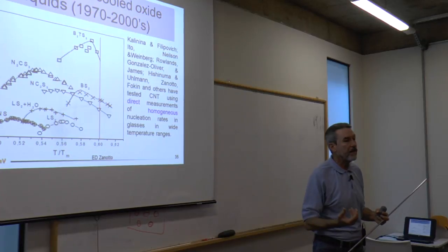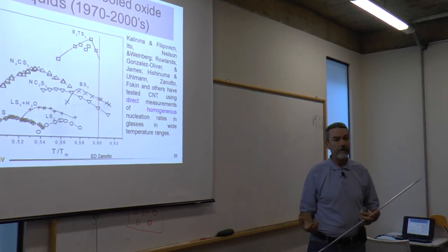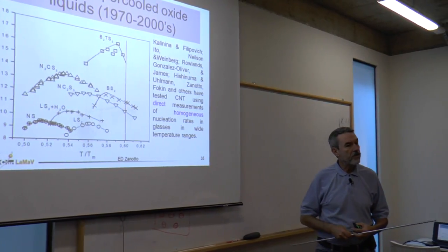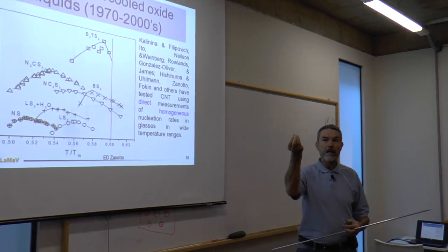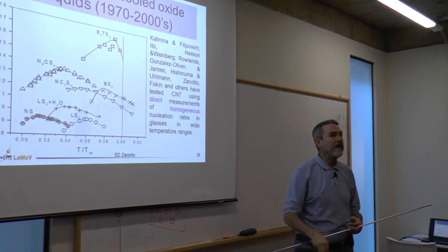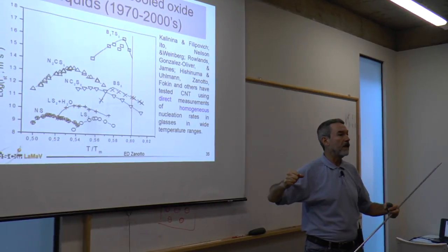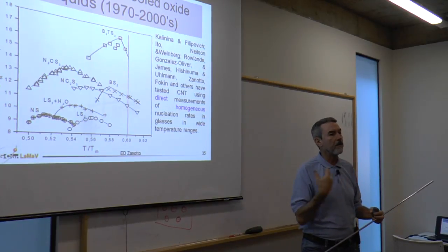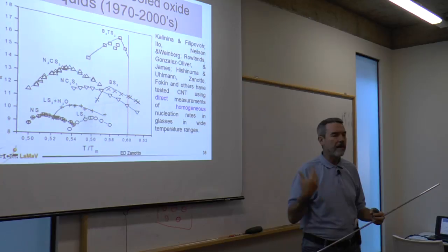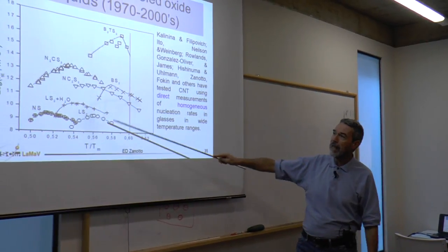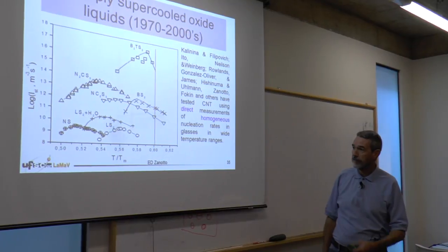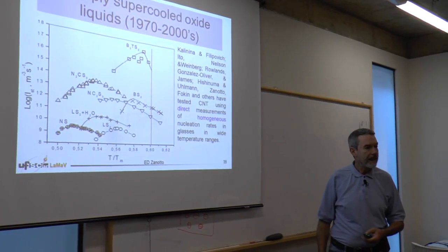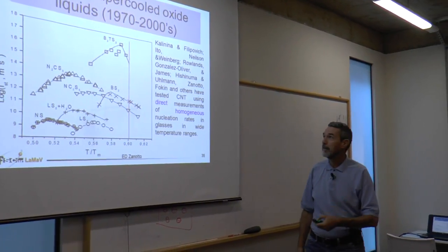And they're very viscous systems, so they're friendly enough, allowing nucleation rates to be measured. Because when you heat up the material for some time, then you quench it, and the viscosity increases so much that you can keep that quenched state and look in the microscope and count the number of nuclei and so on. And repeat several times at several temperatures, one can get these kind of curves. And from these kind of curves, the theory can be properly tested.